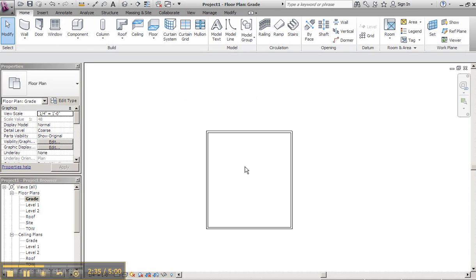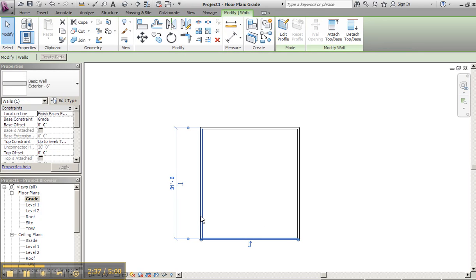Now, I'm going to go ahead and click on this wall. Again, toggle my dimensions to the outside. So I went 28 out to out. And because this is the wall selected, this is the wall that will move when I set this to 28 feet. So that's set.